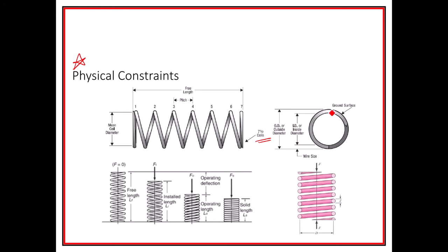There are also the diameters. You've got the outside diameter, the inside diameter, and then you have the wire diameter, or little d. We use big D to represent the mean diameter, dm, or we just use a D, really. So anytime you just see a D alone, they mean the mean diameter. That's the one you use for most calculations, and it's going to be the outside diameter minus one wire diameter, and only one. That makes sense, because the mean would be subtracting two halves of the wire diameter, therefore it's just the wire diameter.